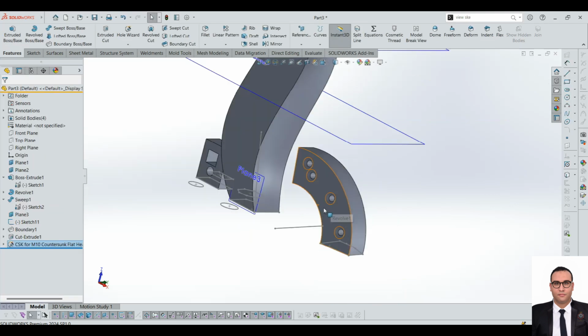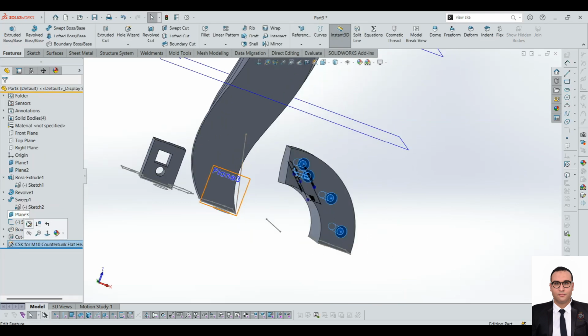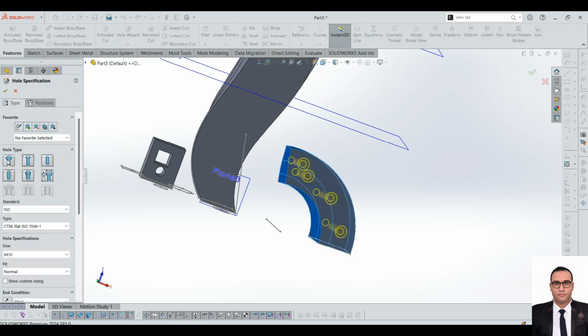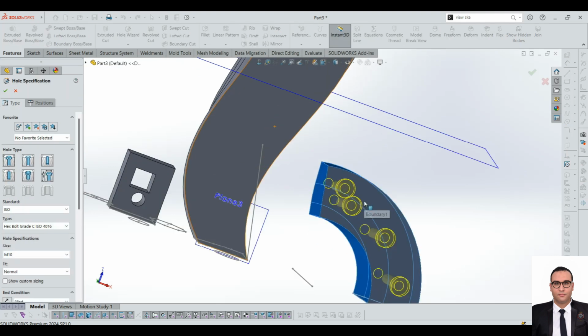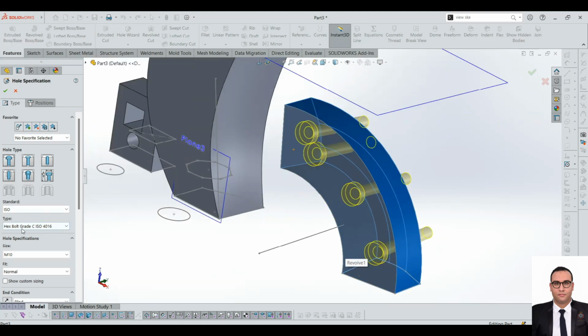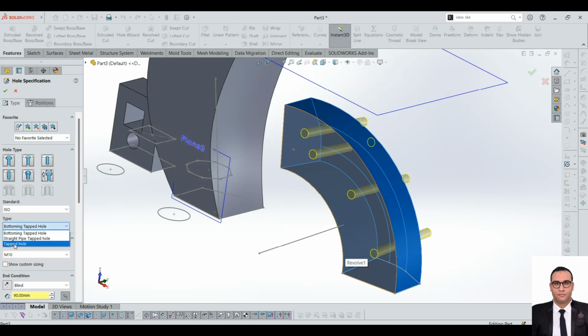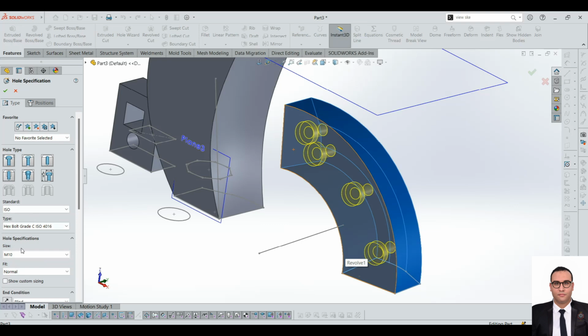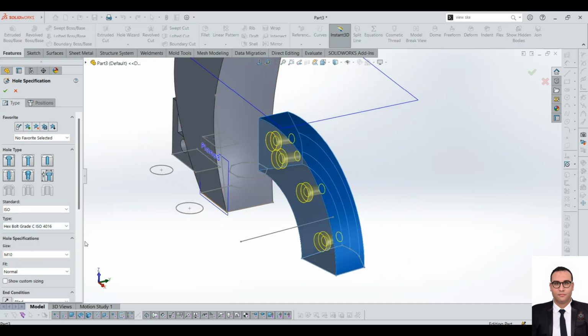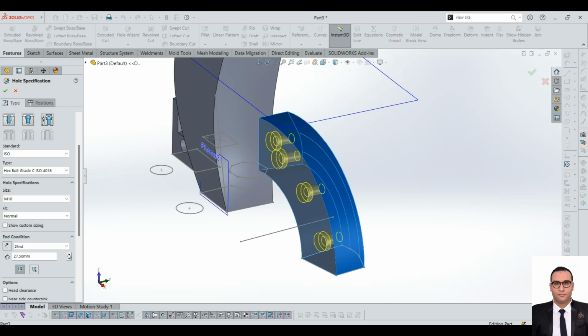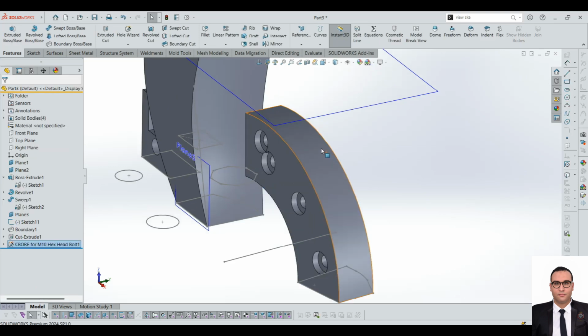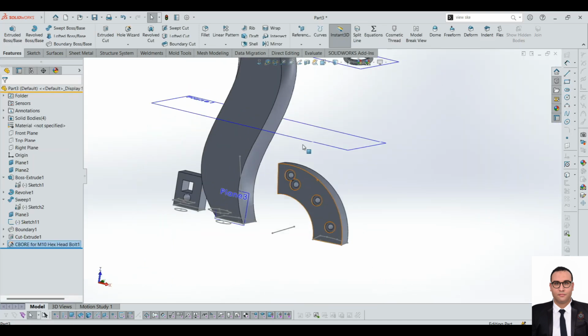Okay, then those are the hole wizard. It will allow us to do almost any hole, depending on the bolt used, and there is a lot of database here. We can use even free holes for threads, as we see here. In this one, you can add holes, which means do the hole, then add the thread at the end, or you can do a complete hole here, and you can add as much distance as desired. Okay, done. Those are holes, how they are done.